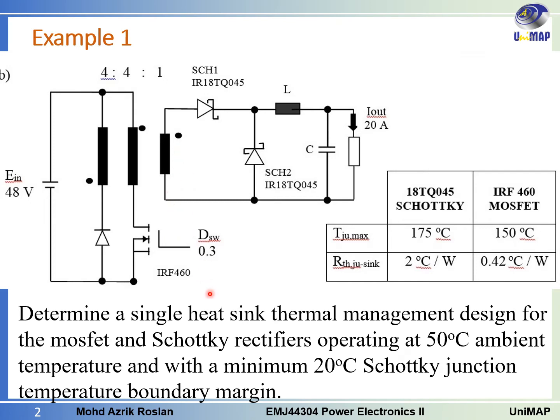So if the question asks for a single heatsink thermal management, it means that we want to select a heatsink on which we will put all three components, two diodes and one Mosfet, on one heatsink. So that's the term single heatsink thermal management design. We will look at how we can design the heatsink that will satisfy all these conditions.